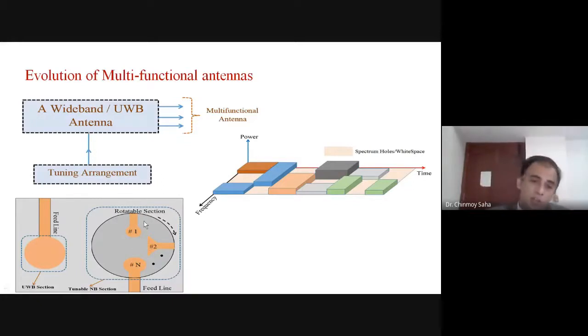When it starts rotating in this direction, for example, as given by the arrowhead, one of these n number of radiators, which are placed in this way along the circumferential direction, 1, 2, n, and so on, will come in touch with the feed line. Each of these radiators is designed in such a way that their resonance frequencies are different.